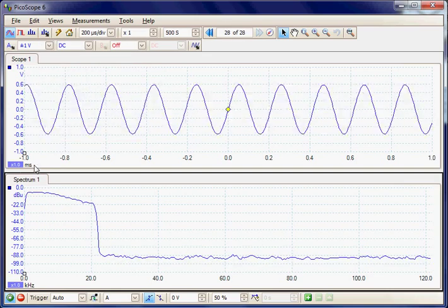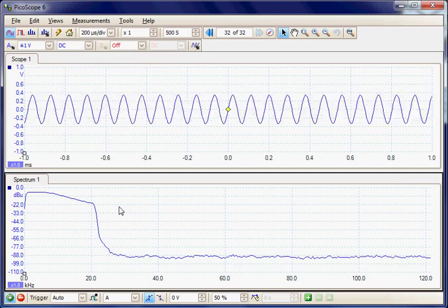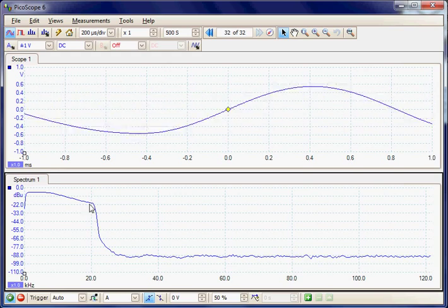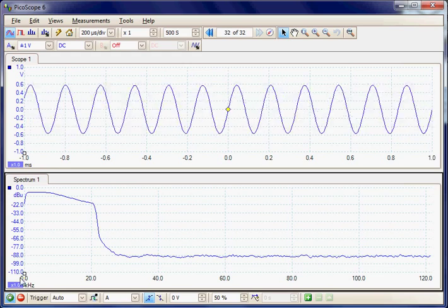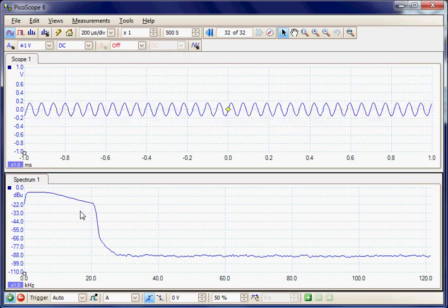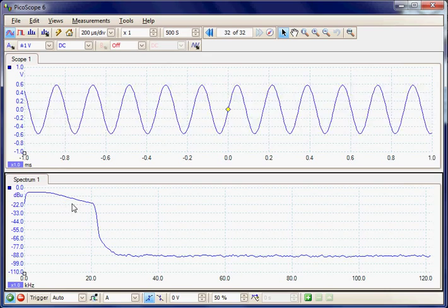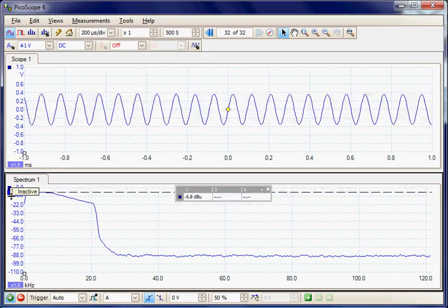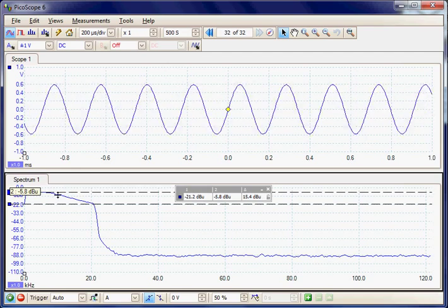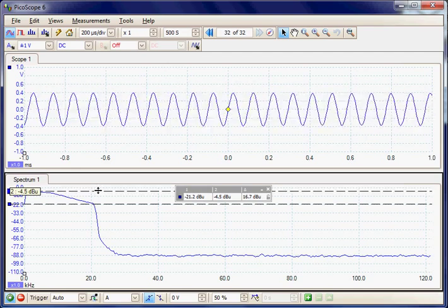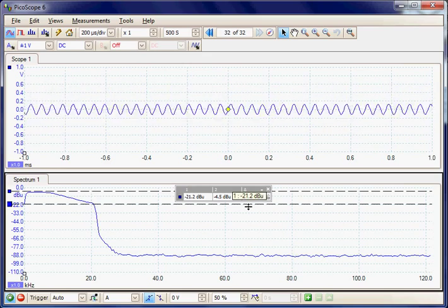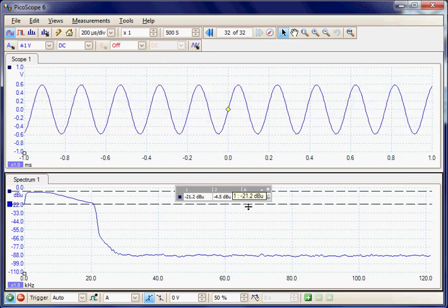And now here straight away we can actually see the response of the filter. So here we can see the HF filter. This is the 20 kilohertz, and this is down at the 200 Hz where we started the sweep, and immediately we can now see, and we can in fact measure the roll-off. So I could put on some cursors, so from the peak down to the cutoff point, that is in fact 16 dBs of a cutoff there.